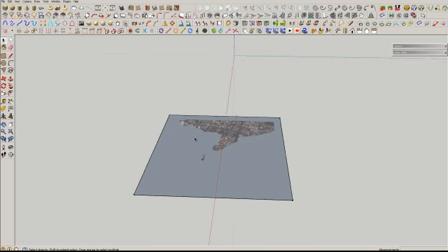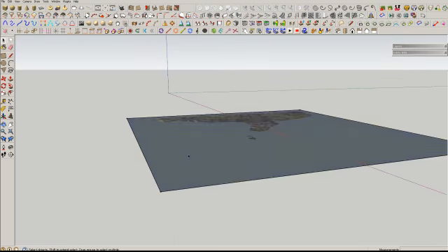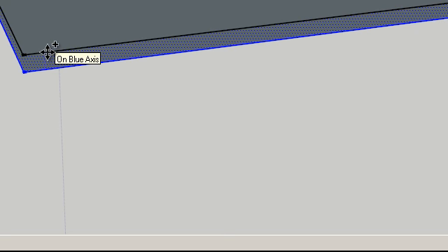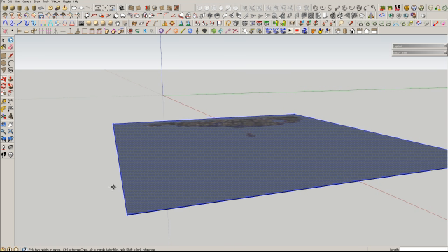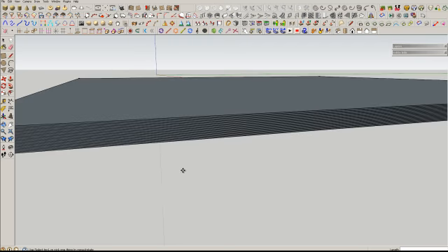So I'll create multiple copies of these surfaces as a reference. I'm going to go for the move tool, take a reference and then move it vertically, let's say by 1 meter. That would be 1000 mm, right? Yeah, so this is one. And what I would like you to do is, instead of copying it one by one, don't exit from the command, don't press escape, don't do anything, don't even orbit, just to make sure that it doesn't have anything. You press X and then you type in the number you want. So I'm going to copy 20 times. Yeah, so this is what we get, right?